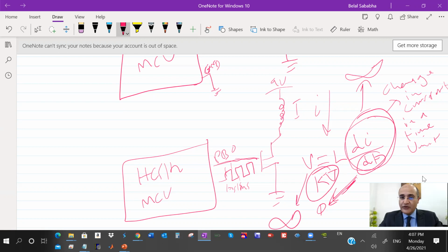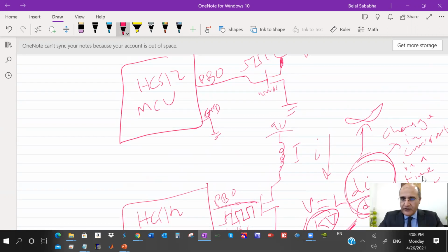Okay. Why would this happen? It will happen because of the characteristics of an inductor. If a current is flowing in the steady state, then you switch off, the inductor will try to create a voltage across itself to make a new current flow in the opposite direction of the original current to save it, because the current is flowing this way, right? If you stop, the feature of the inductor is that it saves current, as opposed to the capacitor, which saves voltage. So it will cause a very high voltage across the inductor to make a current flow in the opposite way to try to equalize it.